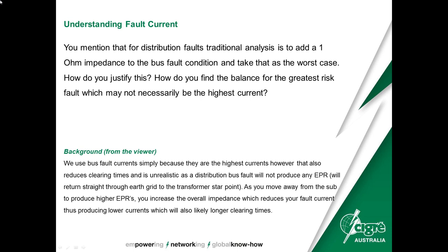There is a clearing time factor in it, but it's largely the class of the substation and its reliability, and then it's just an absolute voltage. So if for some reason you had low fault current on the primary, your secondary was your worst case in terms of current magnitudes. You had clearing times in a bit of a range that meant you had to be in a certain class. Then the only thing that matters now is where your 430 volt contour is. And it becomes less about, oh, the current got less but the clearing time went up. It's more about where was the maximum voltage transfer or voltage gradient transfer.